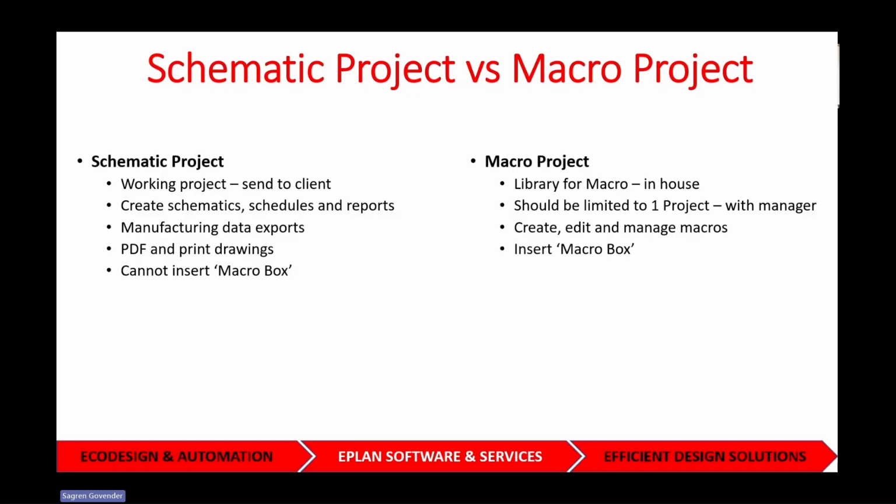You can insert a macro box to manage the macro. So once you have a macro box, you can determine where you want to generate those macros to. You want to generate that onto your local machine, onto the server, so that everyone can access that. So other users don't necessarily need to have the macro project to access those macros. Once it's generated, it resides on your server, and anybody can access those macro projects.